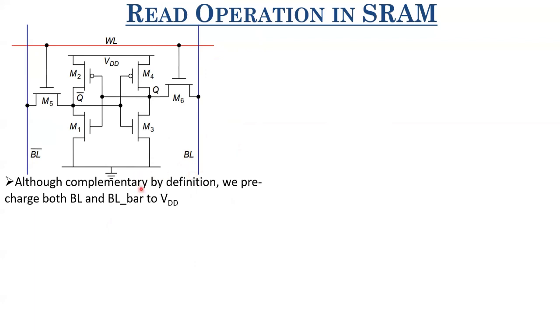So that sense amplifier would also be connected at the end of this array. So the input impedance of that sense amplifier will also be a part of this CBL. What else? So on top, you will have a pre-charge circuitry as well, which pre-charges this bitline and bitline bar initially for a read process. So even the capacitance of that pre-charge circuit would be a component of the CBL.